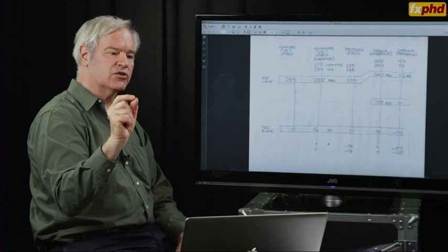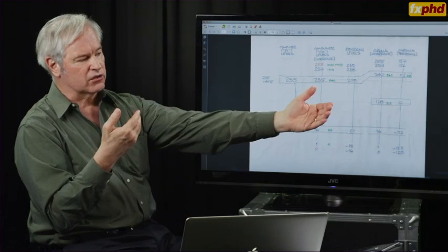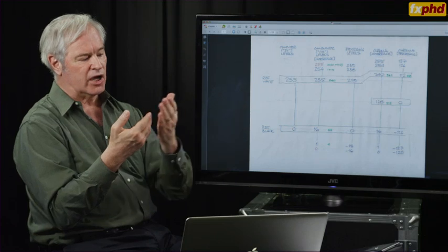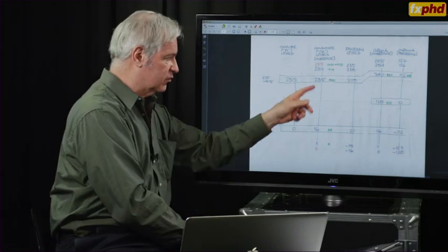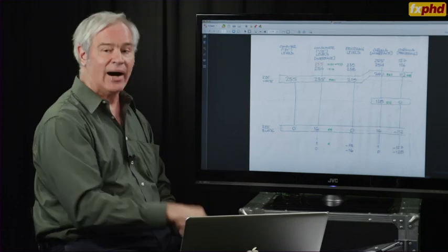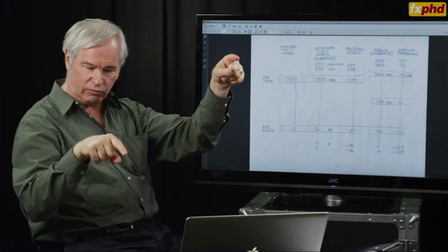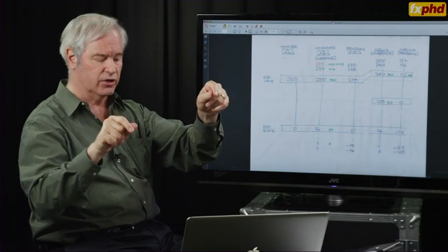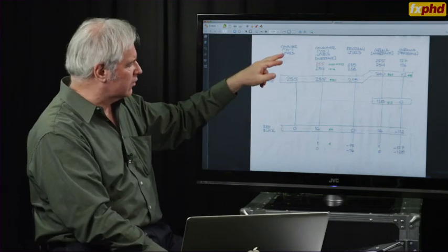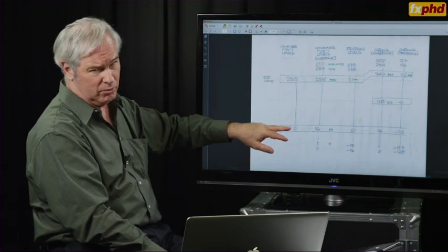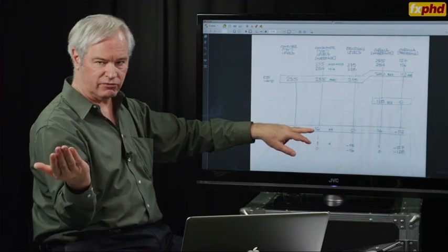And ordinarily, if a source of a signal queries a consumer-level receiver and finds that it's using a standard HD format, it'll ship out the 16 to 235. But if it finds that it's a sort of IT-based 1280 by 1024, say, which is not a video standard, then the source will code up the 0 to 255 range. So loosely speaking, this is called IT, or PC, range, and this is called CE range. But really, it stems from studio video.